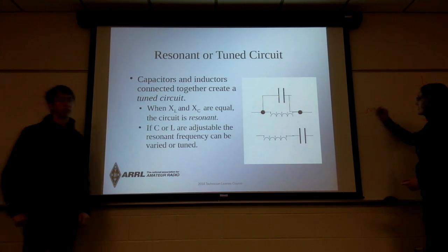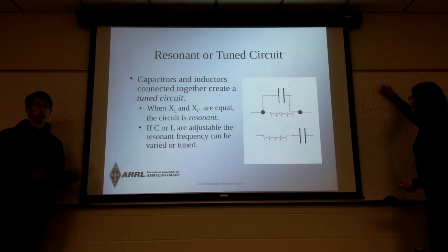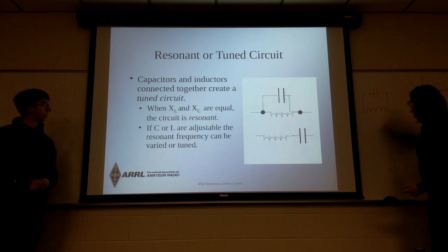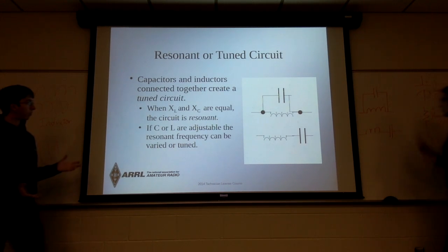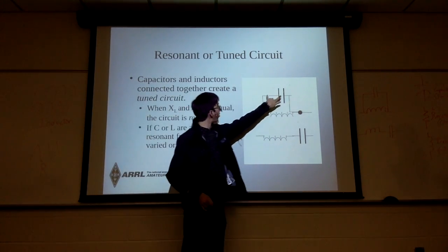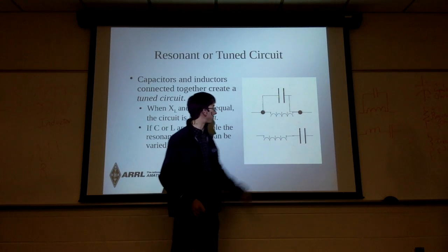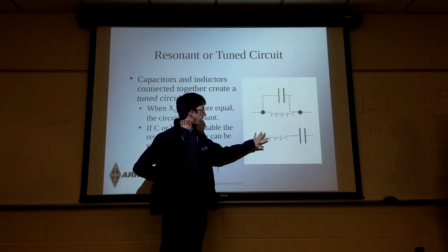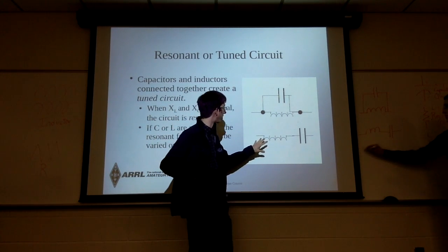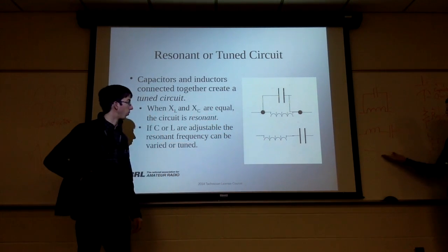Essentially we've got parallel and series LC circuits. LC, inductor and capacitor circuits here. They work similarly. The energy contained in here will transfer to here at the resonant frequency and vice versa. And I was talking about resonance. At resonance, this will be left out of the circuit, which means essentially there will be no current flowing through it.